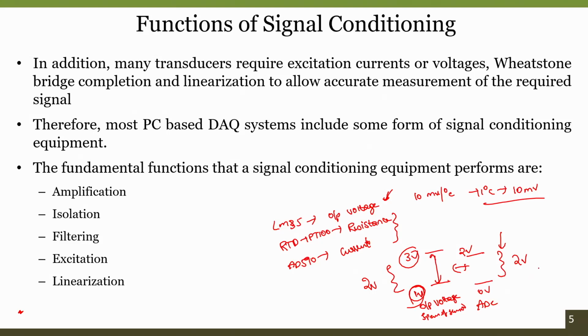But if we can somehow compensate for the offset created by the output voltage, such that we subtract 1 volt from the complete voltage, then the complete span of the sensor will now be 0 volt to 2 volts, which will completely match the ADC span. When we interface directly in such situations, you do not have to compromise on the range of your ADC too.